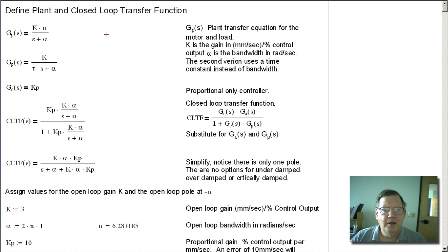Hello. The first system we are going to try to control is a simple gain and low pass filter, or a gain with one pole or time constant as seen here. And what we're going to control it with initially is a proportional gain, but we're going to try three options. One's going to be proportional only, one's going to be integrator only, and one's going to be proportional integrator together. And obviously the proportional integrator together is the only option that is practical, but I want to cover the other two cases first.